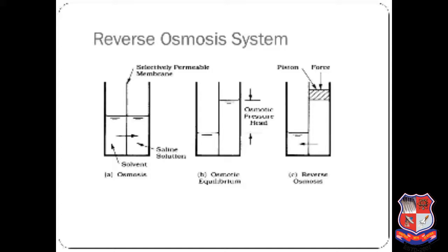Membranes are cast in thin sheets or extruded as hollow fibers about 80 or 250 micrometers in diameter. The advantage of the hollow fiber configuration is that a very large surface area can be packed into a small space because the fibers, although of very small diameter, are technically thick-walled and so self-supporting.